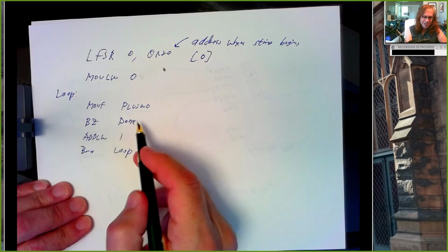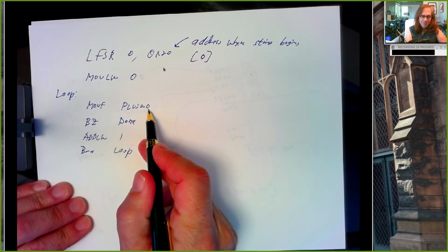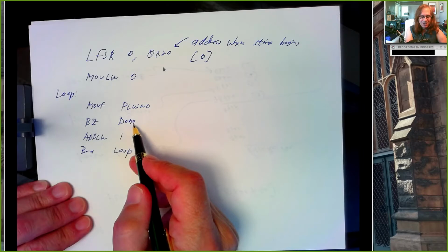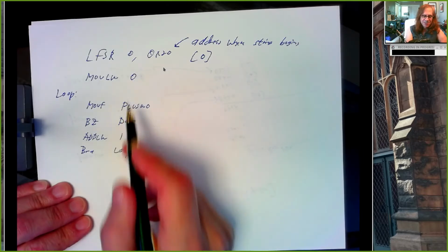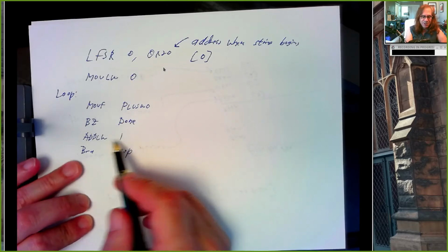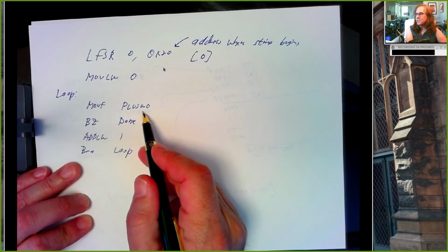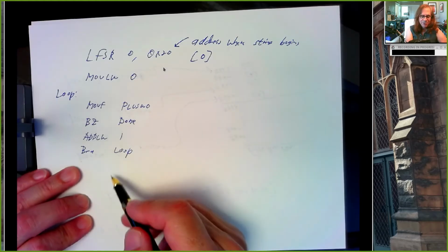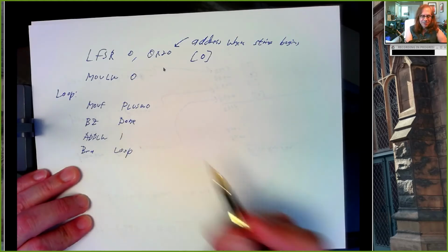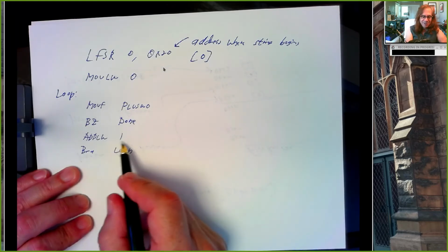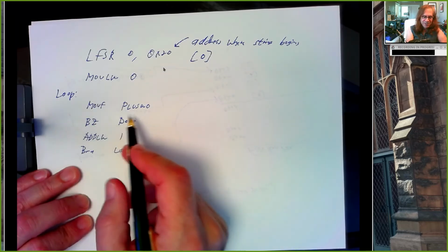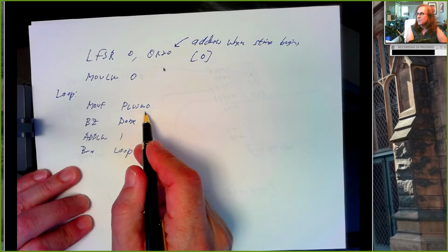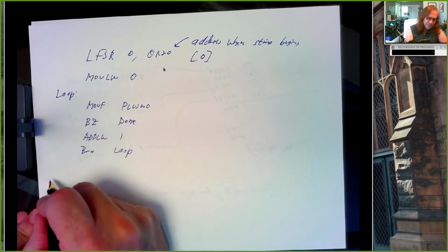So this will look at file register 20. If it happens to be 0, I'm done, and my string has length 0. Otherwise, I'll set W to 1, go back and check character 21. If that's 0, I'm done, and my string has a length of 1. If it's not, I'll increase W to 2, go back and try this again, and this will be character 2, right? The character at file register 22.